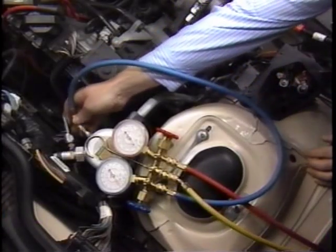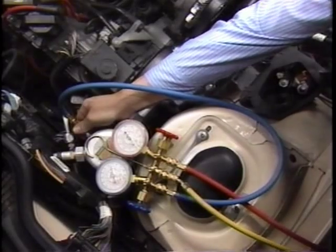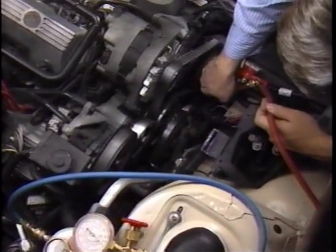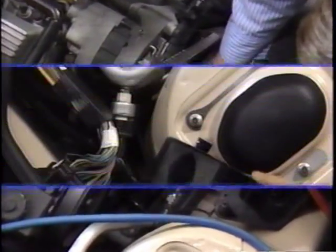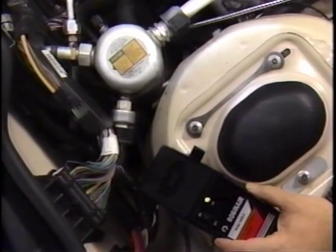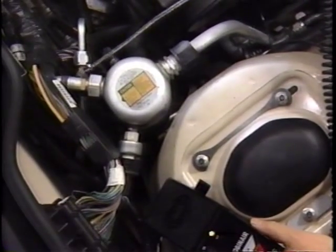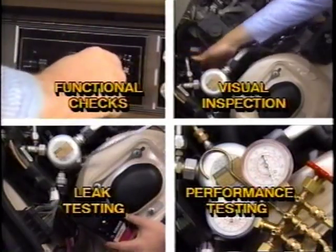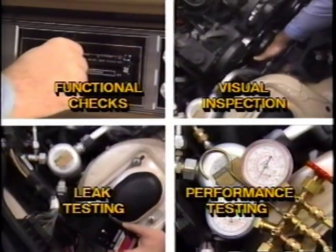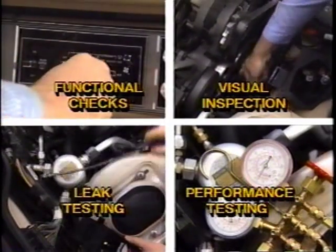If a visual inspection doesn't indicate any obvious problems, then you should proceed with performance testing of the system. Analyzing the results of your performance test should help you to pinpoint the cause of the problem. A leak test is only necessary when previous diagnostic steps have led you to suspect a leak. If so, you may have to perform more than one type of leak test. Following this overall strategy when diagnosing air conditioning problems will help you find the cause of a symptom as quickly as possible. Let's look at each type of testing individually.